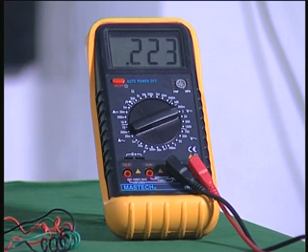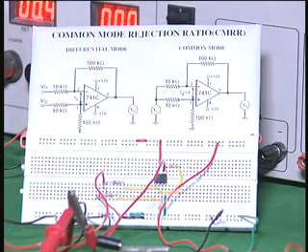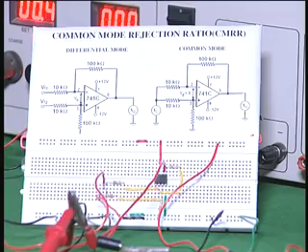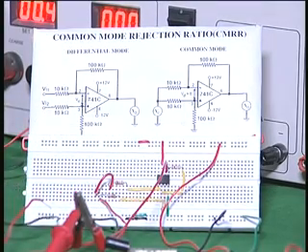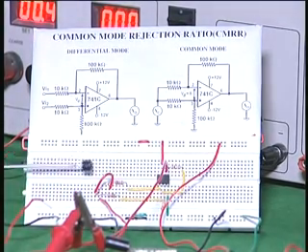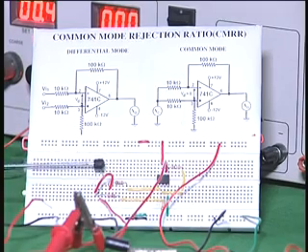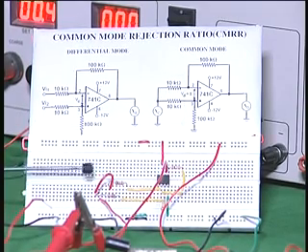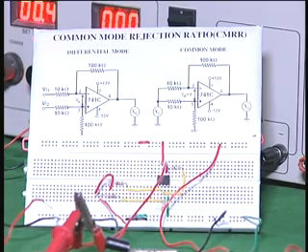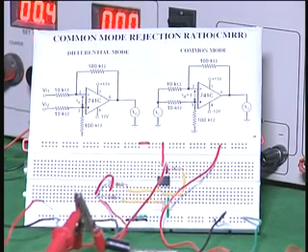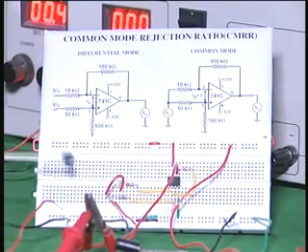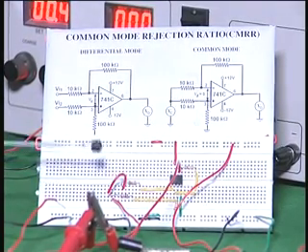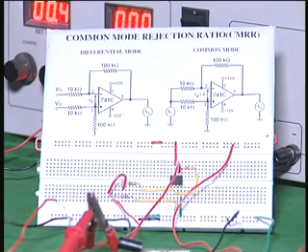Now, what I am going to do is remove these two input voltages, connect the two input terminals together and connect one voltage, the 0.5 volts, alone. Now, you can see there is a red wire which has come in the circuit, connecting the two input terminals V1 and V2, and there is only one source connected at the input, which is already 0.5. I have not changed anything here, therefore 0.5 volts is given at the input. What is the output voltage?